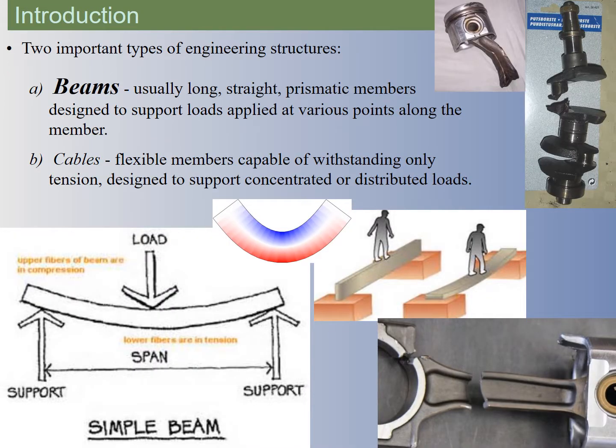Okay, so just a couple definitions. A beam will be a solid piece of material. You'll have some tension happening at one side of your beam with compression happening at the other side. The thicker your beam is with respect to where that rotational axis is, the stiffer it will be. So you can see that the same beam oriented differently will support loads differently. So this is one thing to kind of keep track of.